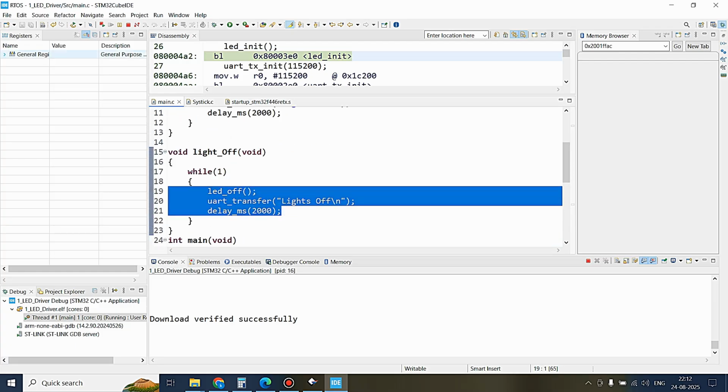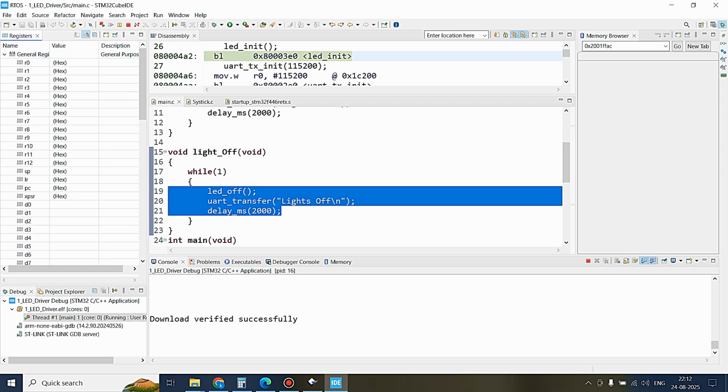The important windows that you want right over here for understanding the internals are the registers window, which shows all the register values, that is the general purpose registers from R0 to R12, and special function registers like the link register, stack pointer, program counter and program status registers. Don't worry, we are going to see each register in detail in a while.